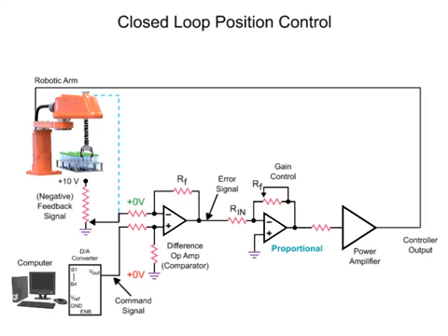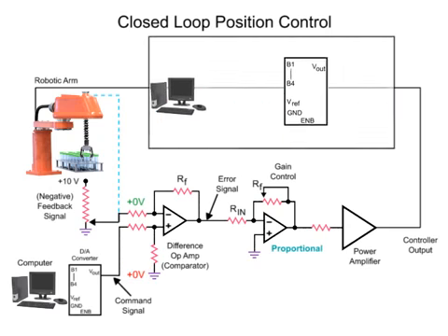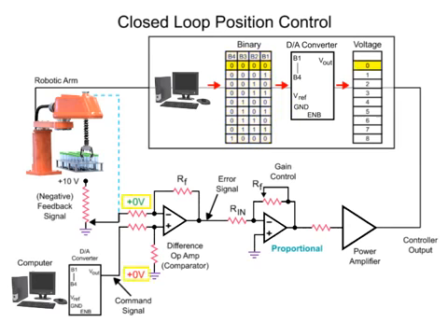For example, with the arm at the bottle pick position, the potentiometer output voltage of 0 matches the command signal of 0 from the computer. To change the arm to another position, a command signal from the computer is required. The command signal consists of binary numbers that increment until a value is reached that represents the desired position. The binary value is then converted to an analog voltage by the digital to analog converter that indicates the position that the arm is required to move.